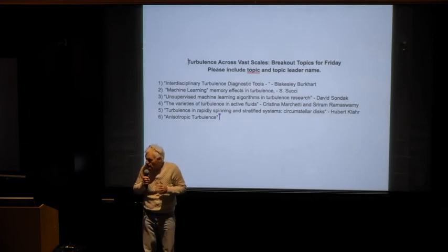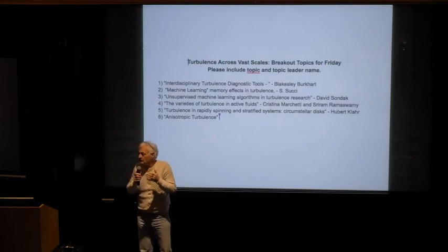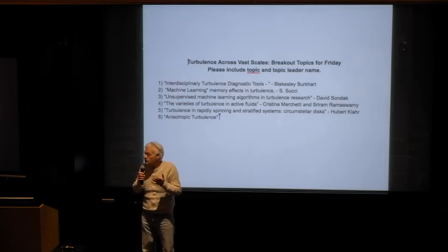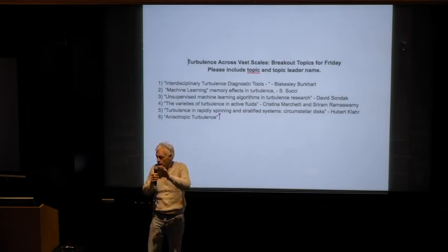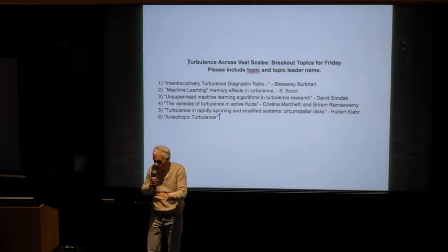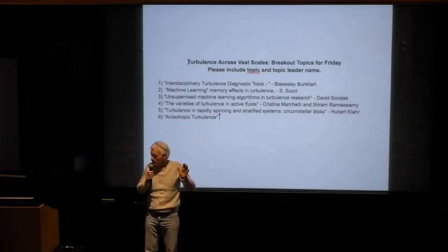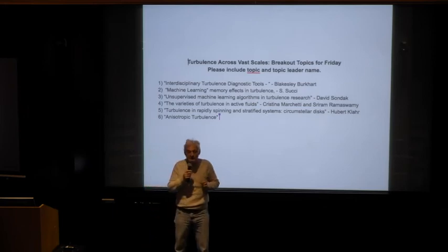And there is no way you can capture this fundamental mechanism if you insist on, I don't know whether you are familiar with rheological constitutive relations, specifying the Reynolds stress tensor as a function of the tensor which I can resolve at the same point and the same instant of time. That is never going to succeed in describing this memory mechanism.